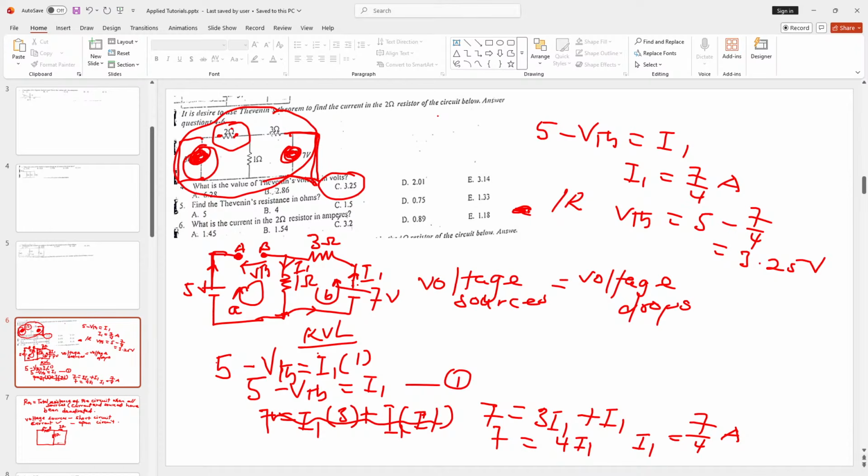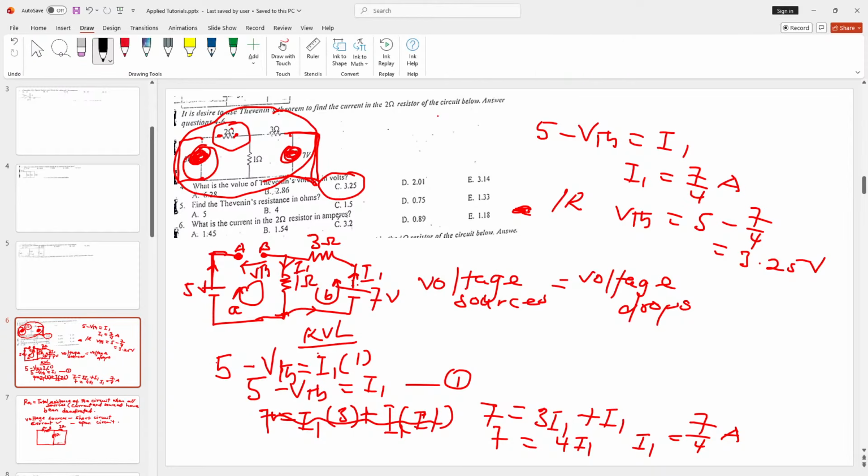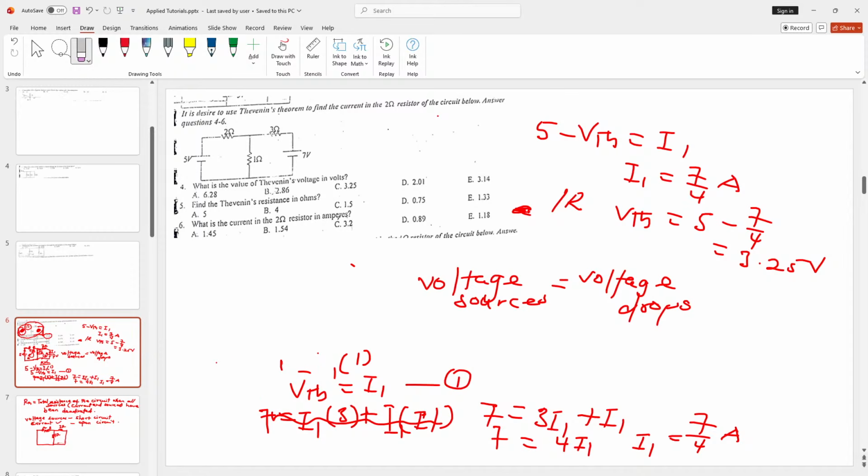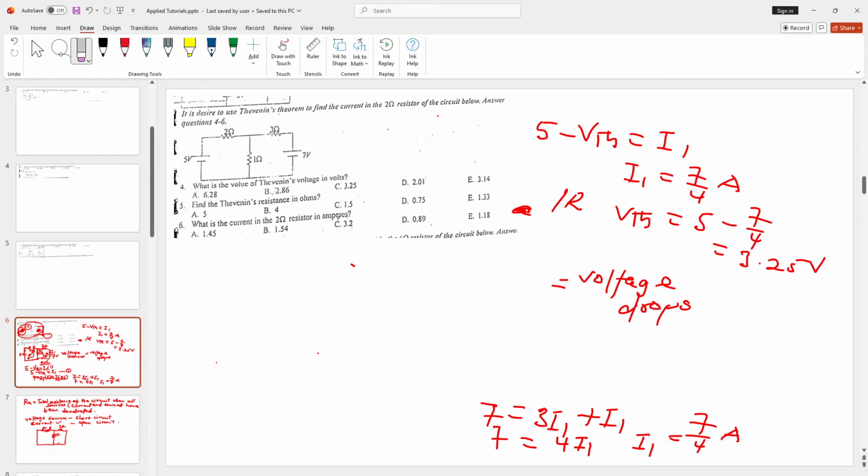But there are voltage sources. In finding RTH, anytime we see a voltage source, we short circuit it. Short circuit is a branch that has no resistance. So anytime you see a voltage source, you draw across that voltage source a branch that has no resistance. That is essentially what you are going to do here. Okay, so let's draw the circuit again.